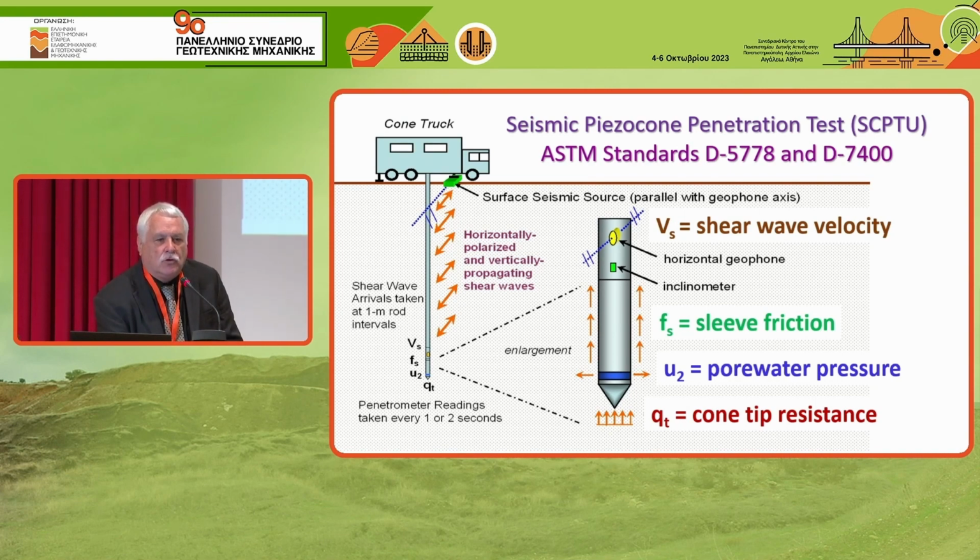So if you are organized, which we are, then it takes us no more time to do seismic piezocone as it does to do cone or piezocone. So this is the minimum test that Georgia Tech will do, just because it was so hard to get up in the morning at 0600, you might as well collect shear wave velocity too.